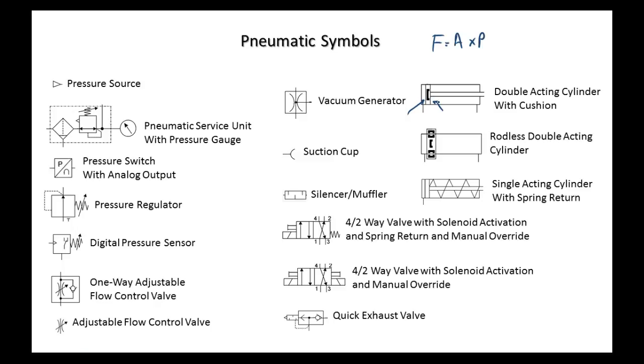And you'll learn how to calculate that if you take fluid power. A lot of times retracting doesn't make any difference unless the actuator is moving something in both directions. That's when it becomes critical. Well, we don't have to worry about that on a rodless cylinder because the area is the same on both sides. Pressure regulator.